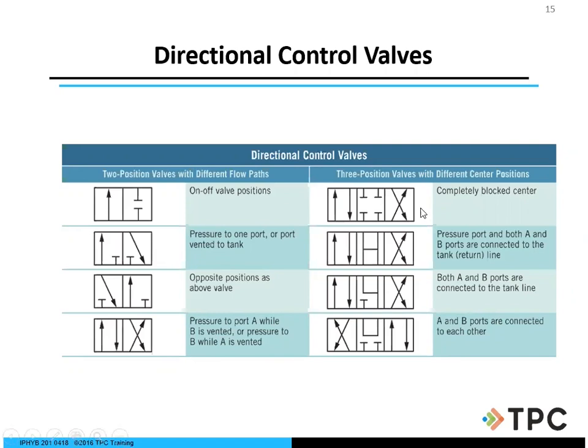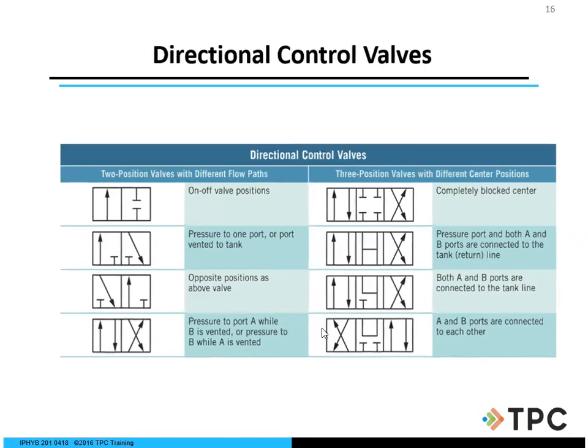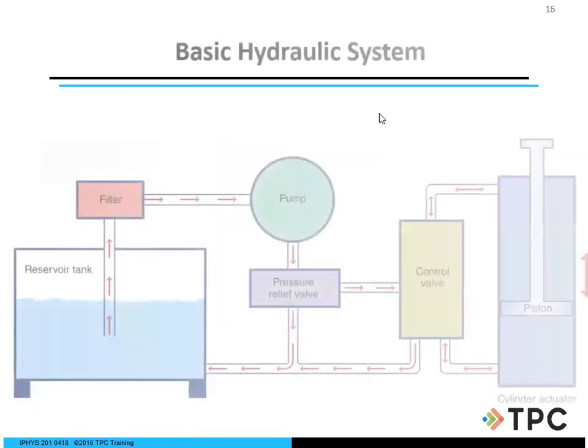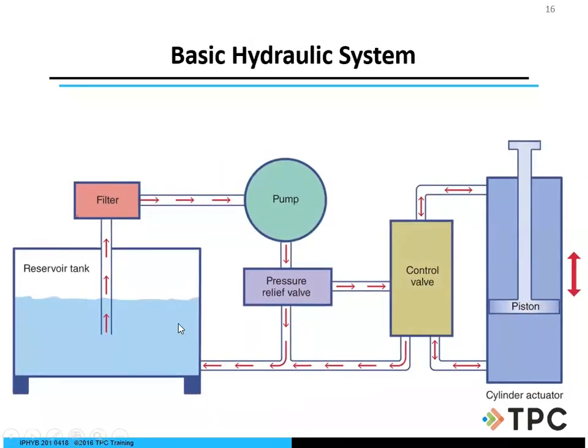All right, so we need to have some other lines when we look at our system, our conductors, our hoses or pipes, relieving that pressure back to the tank. That's critically important when you're working with 3-position, 4-way directional control valves in this regard. Obviously, you do see these here going back to the tank over here. That's going to determine what size pump, what size motor, what type of pump, what type of motor I'm going to have for my hydraulic system. These guys over here are 2-position, for smaller applications that we do work with. And again, this is our basic hydraulic system here.